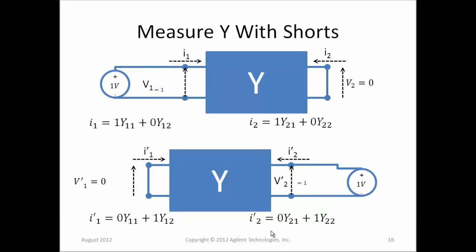So welcome back again. I think you've discovered that one of the weaknesses of Z parameters is they're not defined for a series impedance. But you can use another variant on the Z parameter theme, which is Y parameters. This is admittance parameters, which is the inverse of the impedance parameters. And you measure these most conveniently by putting shorts across most of the ports and a voltage source instead of a current source across the powered port. And this is a very convenient way to measure Y parameters.